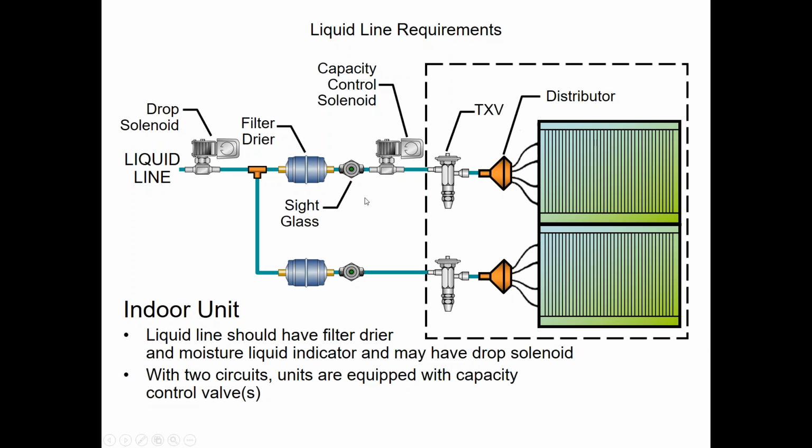Okay. All right. One of the other things I wanted to add here, since that question did come up, is the drop solenoid in this position. We don't recommend it with our condensing units or condensers anymore. We used to a long time ago with our 38AH units, and prior to that, the ADs and AEs for all the Carrier people that worked on the old units. The drop solenoid was used for single pump out control.